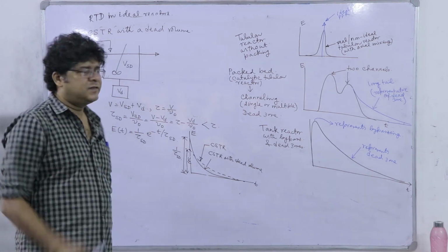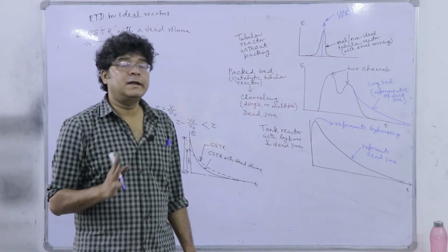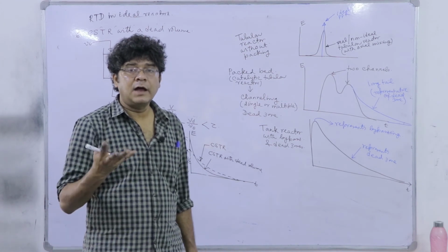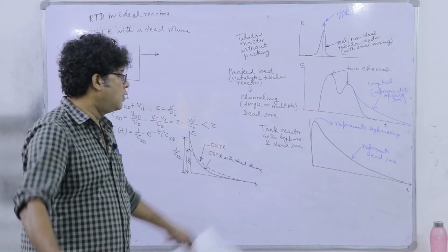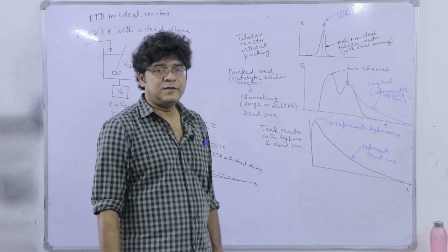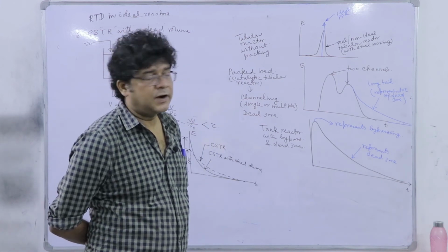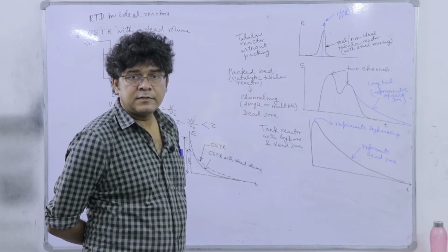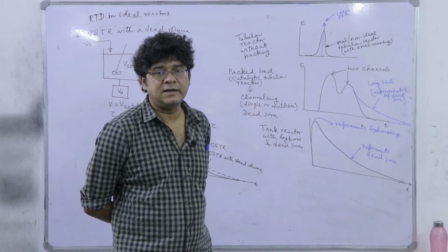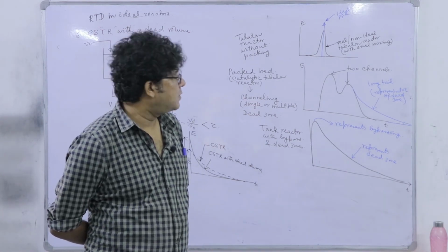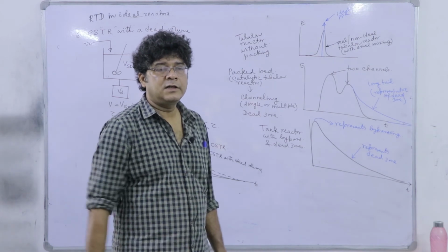So, that is some diagnostic approach, non-quantitative, some qualitative diagnostic approach, that if I have this sort of RTD curves, you can identify what is happening inside the reactor, what non-ideality actually cropped in the reactor during operations. It may happen that over this initial period after commissioning, the reactor is providing its full duty, generating output which is exactly equal to the design conversion, but with time this conversion drops. So, definitely we have to note that either there will be a bypassing or there will be formation of dead zones and something like that. Some non-ideality is actually being generated due to operations, due to heterogeneity in the packing, due to some malfunctioning of the stirrer in this tank reactor.